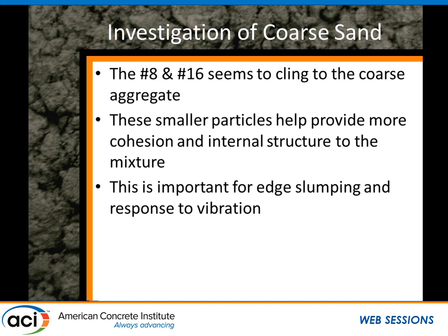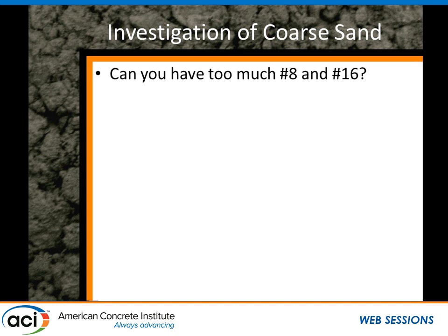These smaller particles help provide much more cohesion and internal structure to the mixture, and this is important for edge slumping and the response to vibration. We'll talk more about that coming up. So if a little bit's good, well then more must be better, right? We should try to add a lot of this number 8 and number 16 and see what happens.